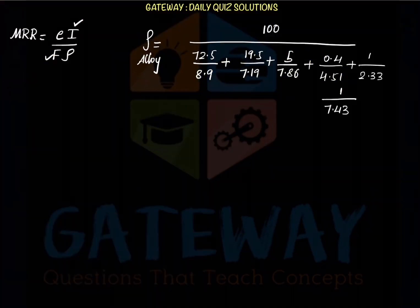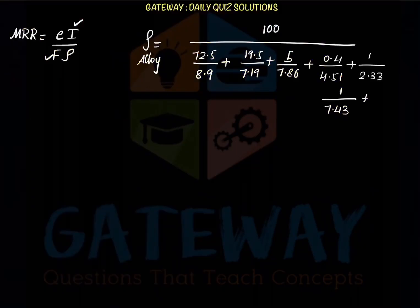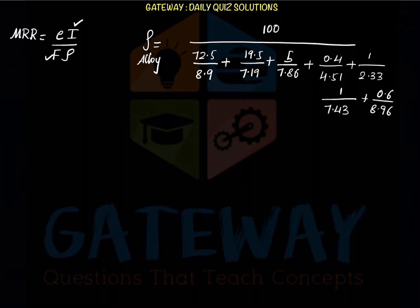And after that we are using manganese, and manganese also at 1%, upon manganese density 7.43. And finally it is copper. Copper is 0.6%, so 0.6 upon the copper density 8.96. So in this way we will be calculating the density of an alloy.